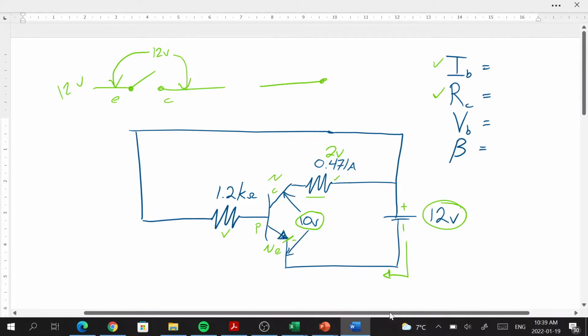In contrast, if you have a closed switch, and again we can imagine that's the emitter and that's the collector connected to 12 volts. Well, if you took a measurement of the difference in potential across it, you would read 0 volts. There's no potential difference now that the switch is closed. Now, a transistor works a little bit differently. It's almost like a rheostat.